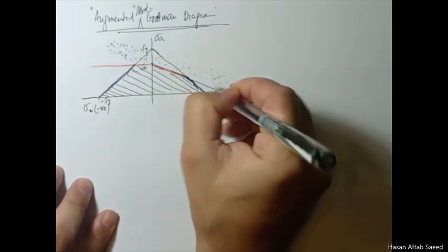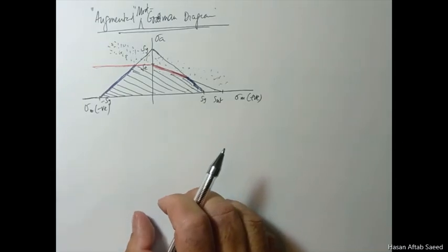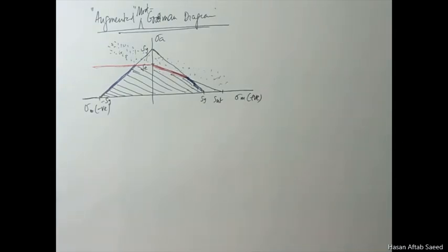So this diagram is called the augmented modified Goodman diagram, or augmented Goodman diagram, and this one should be able to take care of all your situations of stress, whether they are positive mean stress or negative mean stress, or whatever the value of sigma a.